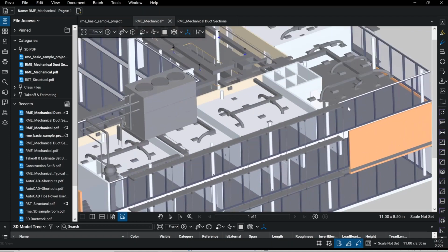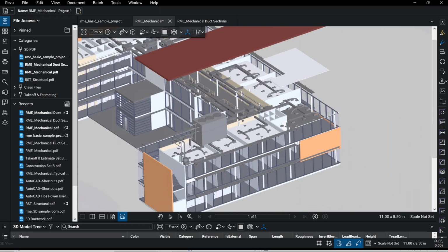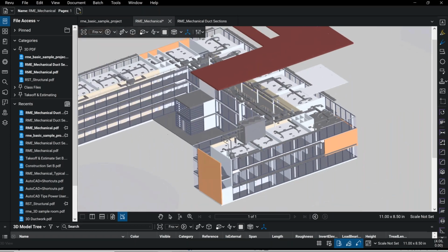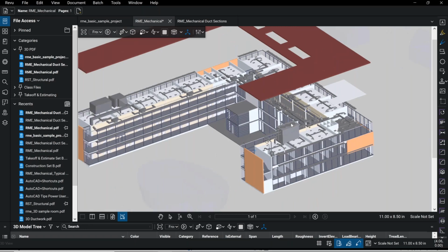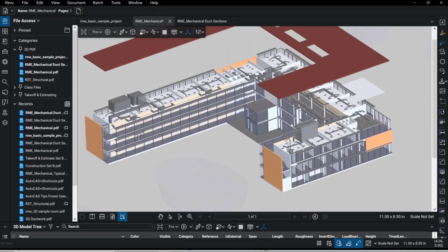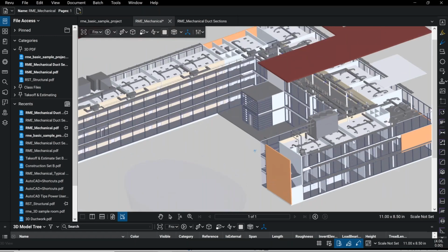The next model we're going to look at is going to be just a 3D view of one of these rooms here. So with that crop box feature, it will crop your model, but to be honest, it's not as easy as it looks to kind of create a little cropped view. In Bluebeam, you can go ahead and select things that you would like to have in a view.